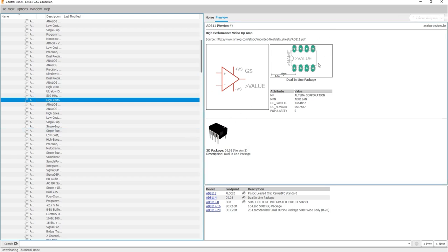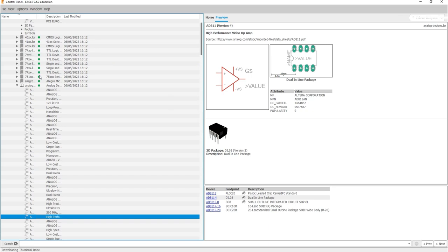The green marker behind the library entry indicates that this library is in use. This means that it can be used in the current project. Devices in this library will be examined by search function in the Add dialog of the schematic diagram or of the layout. This makes them available for the project. The library will not be examined if the marking is gray.